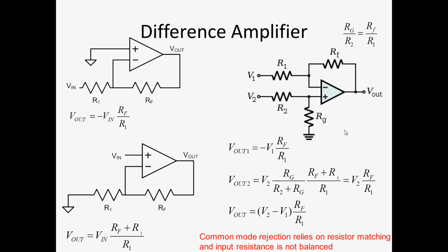There's no such thing as an absolute voltage potential. Potential is always relative to a reference. That is why you take measurements using a differential amplifier. You decide where your reference is. It could be the saline bath if you're doing some cellular electrophysiology recording, or in the case of EEG, sometimes it's the tip of the nose or the linked mastoid or one or both earlobes, all these kinds of things.